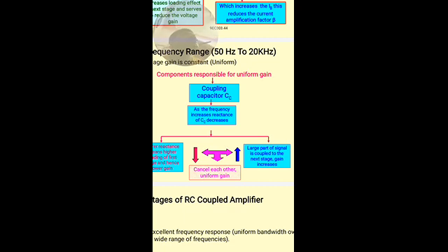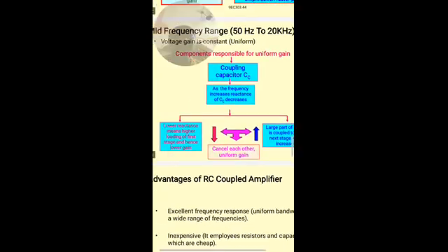One increases the gain because of the low reactance: most of the signal is coupled from one stage to the next, so that signal gets amplified further, shown by the blue arrow. But with the decrease in reactance, the loading effect increases, and that reduces the gain. So two things happen simultaneously, gain increases and decreases, so the resultant gain remains constant in the mid frequency region.